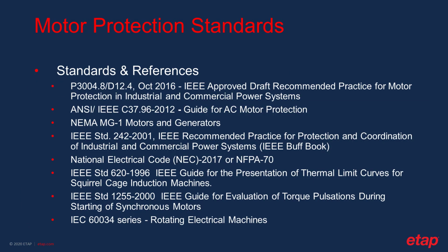If you like to have further information regarding this typical scheme or suggested scheme for protection of the motor, this standard IEEE P3004 is a good one for reference. Also, the C37.96 guide for AC motor protection is a good reference for motor protection.